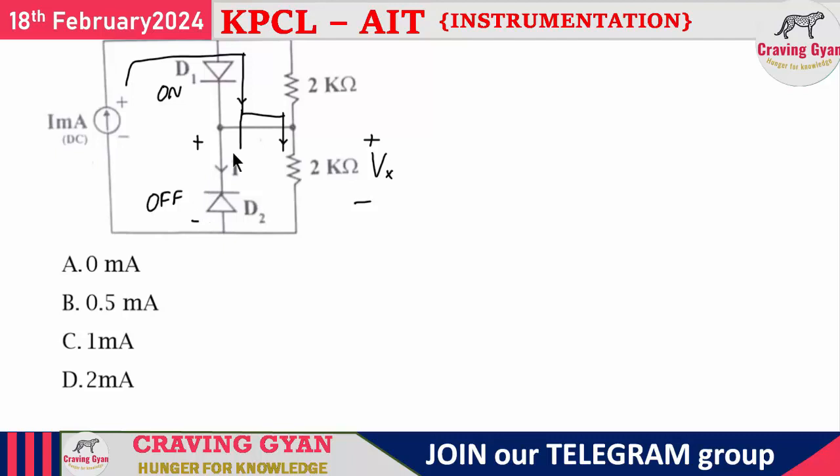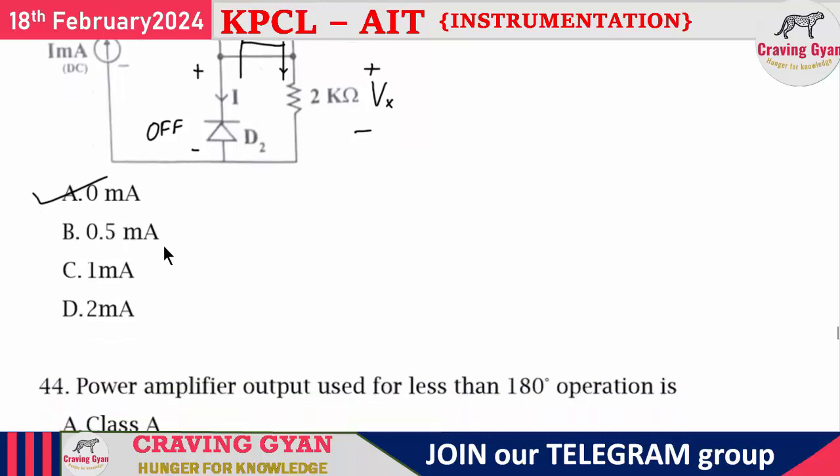D2 is in the off state, that we have proved. So in the off state, what is the current? The current is roughly equal to 0 milliamperes or 0 amperes, right? Strictly speaking, the current is in the order of microamperes, but all the options are in milli. So I am going to opt for the first option, that is 0 milliamperes.